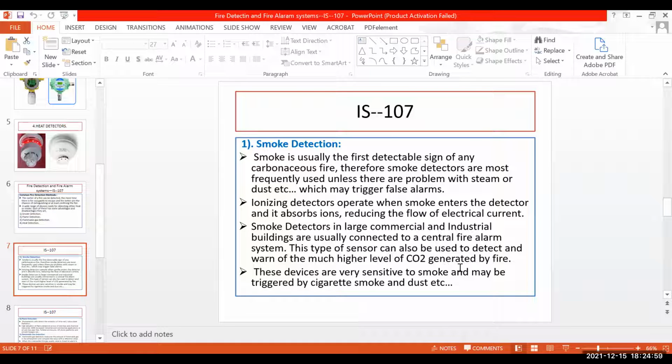I'll share how it will be. And in some locations in the construction phase, if the project is medium or large scale, we will normally be using this for containers and office porta cabins, because all the offices are interlinked. Based on the size, we'll be using the fire panel to identify where the smoke detectors have started alarming.